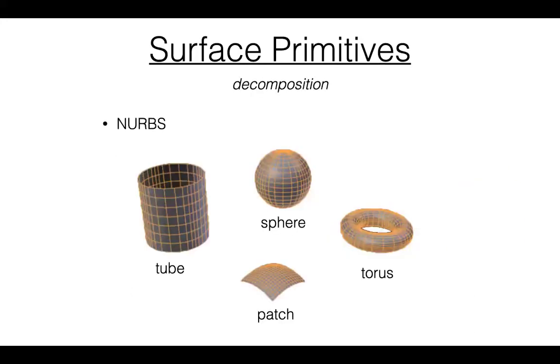And then these surface primitives are actually the general decompositional representation of higher level compositions, where here we have curved cells. It's not a piecewise linear decomposition, but in some cases we can precisely give the geometry through these NURBS, non-uniform rational B-splines.